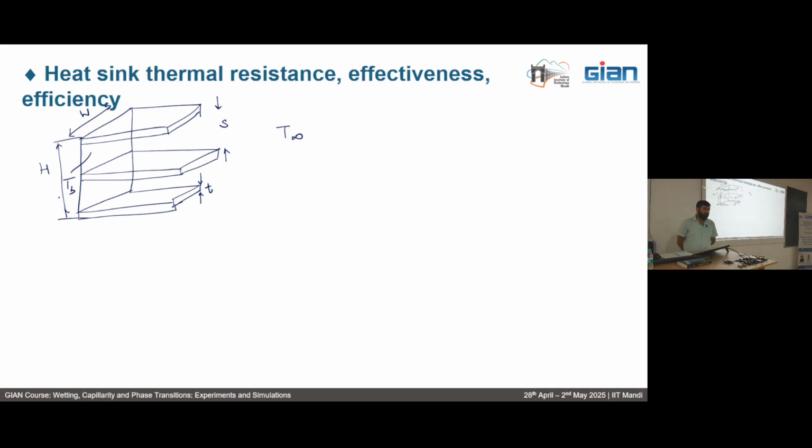So if I have to write the net thermal resistance of this heat sink, what would it be? So the heat transfer, is it in series or parallel here? Parallel, right? It's parallel.